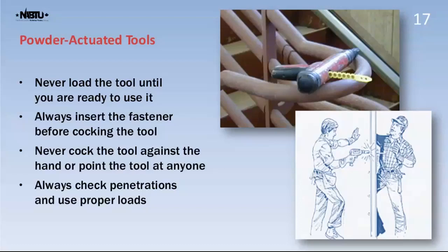So this one's yellow, there's red and different colors. And so depending on the strength and the amount of powder, which shoots it harder and stronger, you want to make sure that you get the right strength for the substrate that you're shooting into. Again, it's all about training, guys.